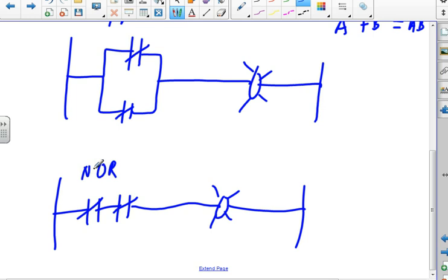Okay, so on page 91, we've got some pump bringing stuff into a tank. I got a high level, I got a low level, I got an outlet valve, I got a heater, and I have to control what the tank is doing. The only thing I'm missing on the tank is a mixer, so I should probably throw in a mixer too. On page 93, I show that same diagram. So I have the same tank with a pump and a high level, a low level, an output valve, a temperature switch, and a heater.